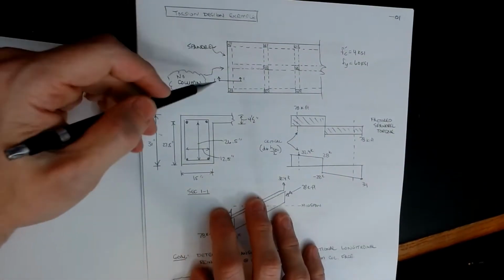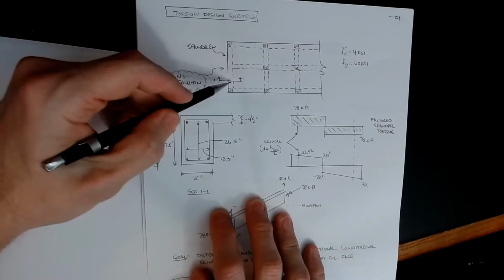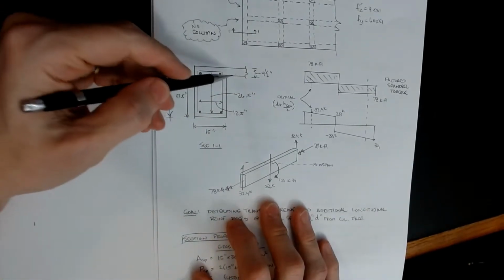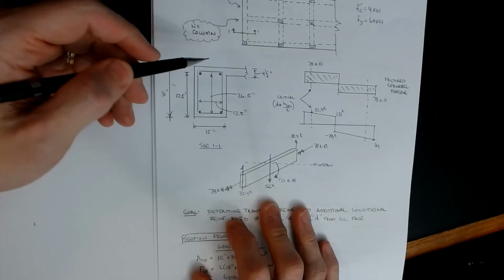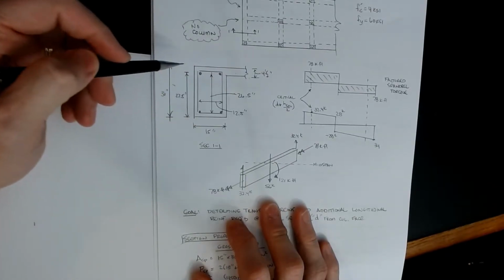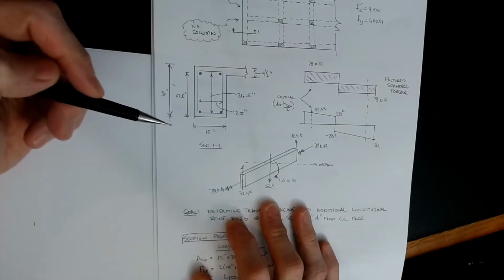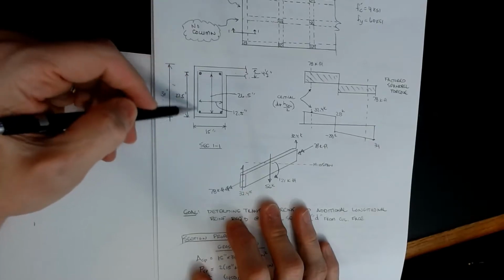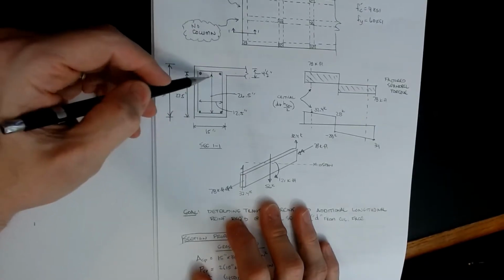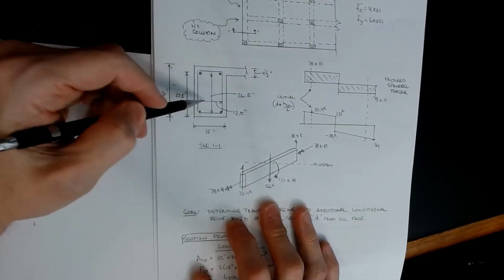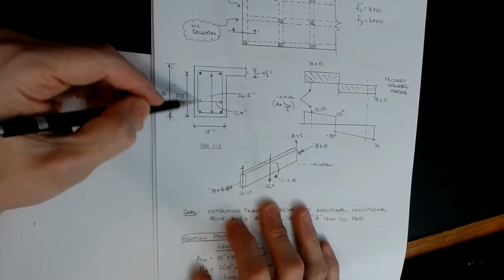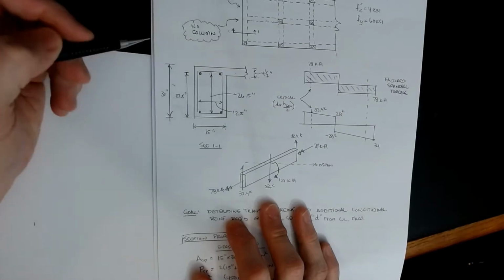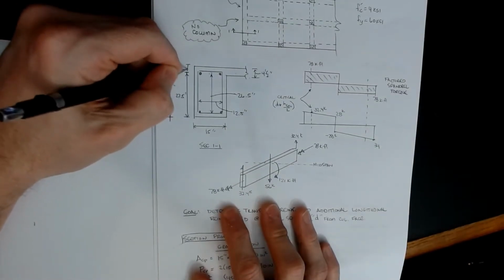Now if I look at a cross section through the spandrel beam at location 1, this is the picture you get. We have a 4.5 inch thick concrete slab that is integral with a beam that is 30 inches tall and 15 inches wide. The reinforcing is such that the cage, or the area bounded by the stirrup, is 26.5 inches tall and 12.5 inches wide. The top of this d dimension is 27.5 inches up from the bottom, so there are 2.5 inches of cover here.